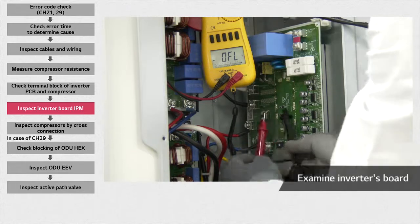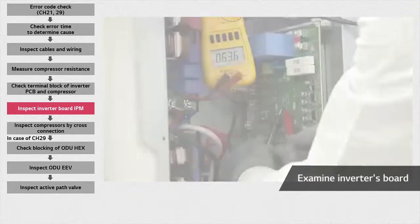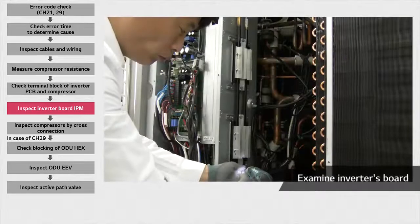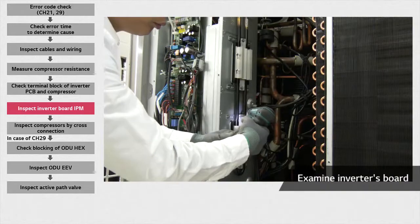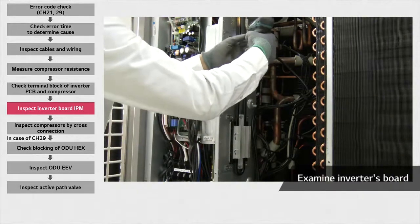First, check the DC voltage, then compare it with normal voltage value. The voltage should be checked as shown in the figure and compared with the values in the normal range as shown in the table. Next, check the tightening condition of the inverter board's heatsink. If the screw is loose, you should tighten it firmly.